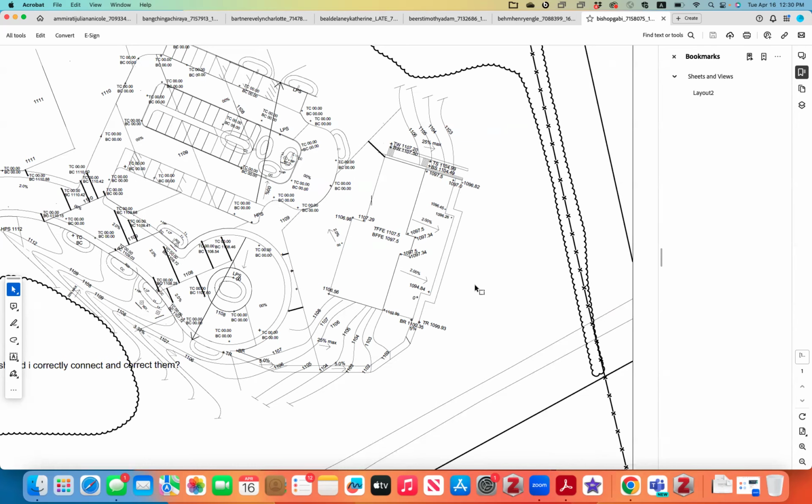Plot that out, revise the TFFE and BFFE, and just offset them by 4 feet and see how much you have to push back to fit all those contours. You would have a little bit of a challenge back there, but I don't think it's not doable. I think it's doable. If you run into difficulty, you can watch that portion of the review. Okay, sure. All right. No problem.